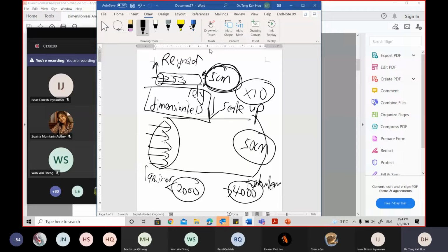That's why the Reynolds number has been introduced, which is dimensionless. That means if you calculate 2000, either here or here, it's still laminar, regardless of all the dimensions mentioned here. So that's the main purpose why we need to learn dimensionless applications.